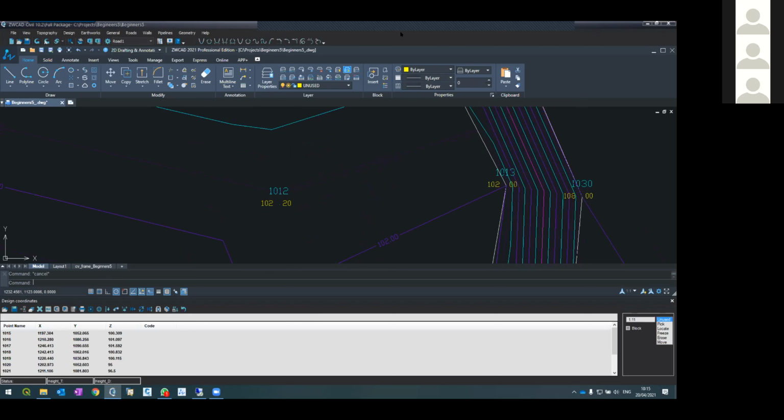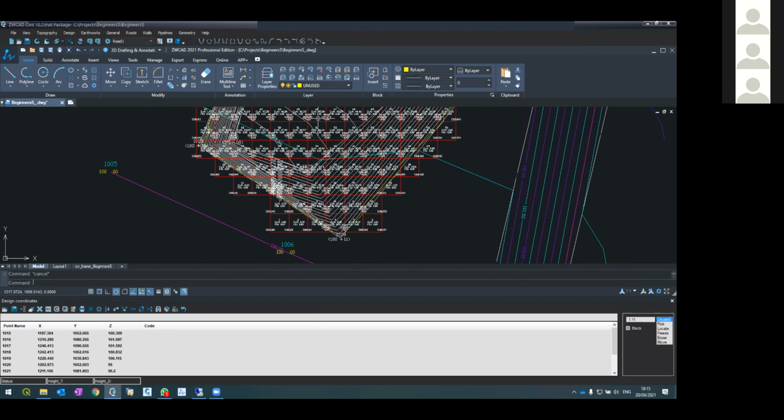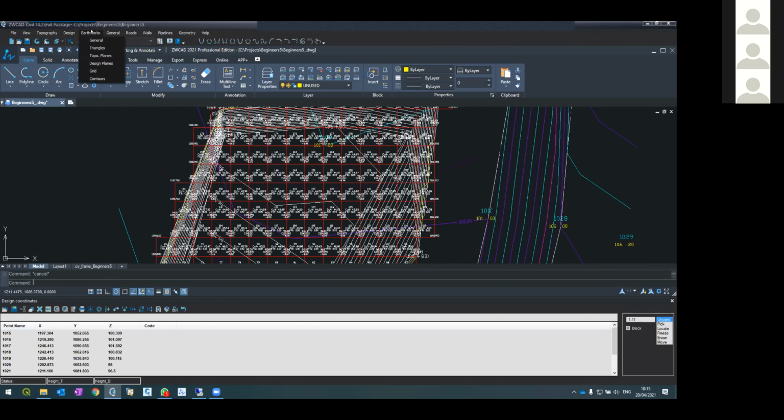One second. Showing this file. And we created contours for the design. In this case, it was a pit hole. And from that, we went into earthworks and calculated the volumes between the two surfaces, getting the volumes of the excavation of the cut, which was done over here. Then we said, okay, we have a figure of the earthworks quantity, the volumes. But how do we